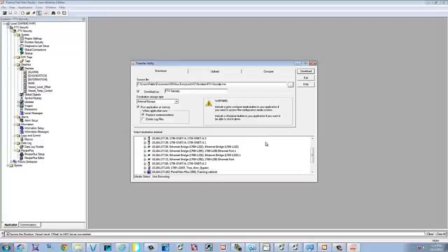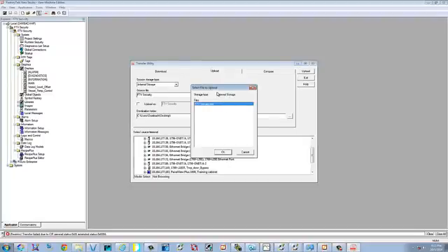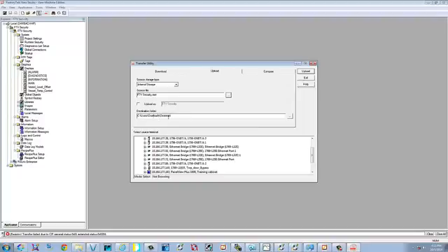Okay, now that the PanelView has booted back up, we want to retrieve that same file. So we're going to go to upload, which is the middle tab. We want to select internal storage, and then we're going to search that PanelView and see what's on it. Up pops the internal storage and what files are on it. We're going to select this MER. We're going to place it on the desktop. You can put it anywhere else you want, but I just have it selected for the desktop.